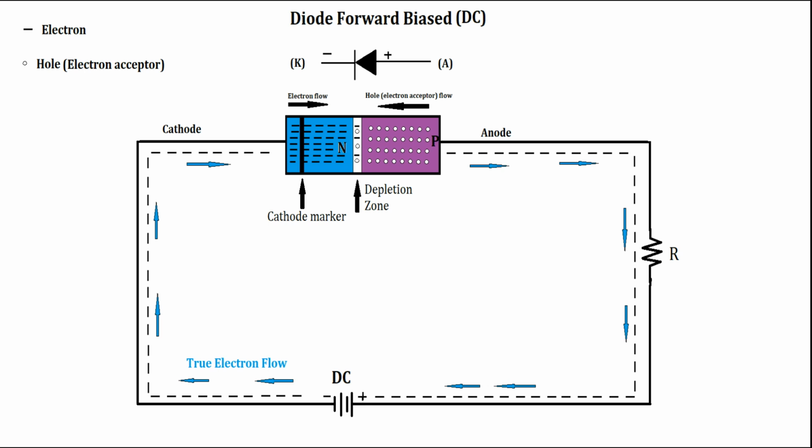Without getting too detailed with the chemistry, we'll just go with the electrons in the N region are not very active when there is no voltage applied to the circuit. Once you apply voltage, electrons flow. Remember that electron flow is current flow and actually goes from negative to positive, not the conventional way, positive to negative, but the true way. So they build up in the N material, but because of the PN junction where the depletion zone is, there is resistance against letting the electrons through.